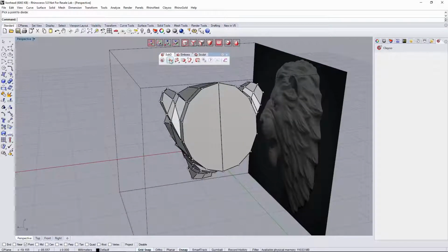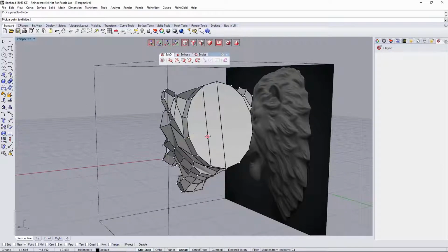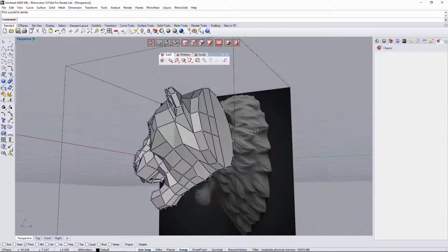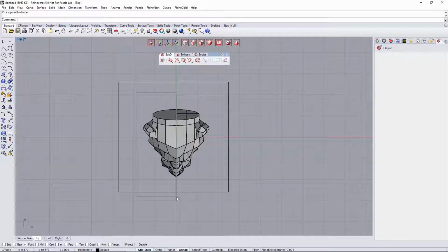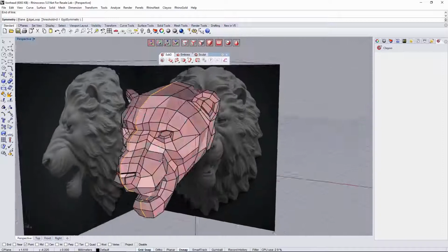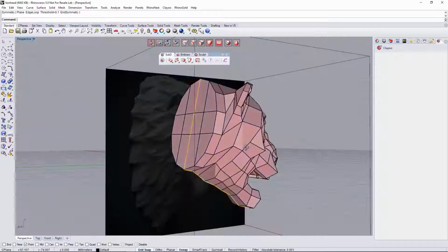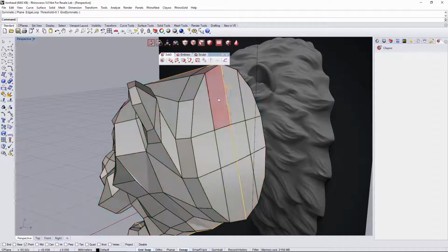Anyway, what I recommend is to finish and have all quads in here. So I'm gonna do something like that, maybe something like this, and something like that. Okay, now from the top view, what I'm gonna do is I'm gonna get rid of half, like that, delete, and I'm gonna select the other one, addition, symmetry. Now I can go by plane from here to here and right click. Okay, now it's symmetrical one more time.